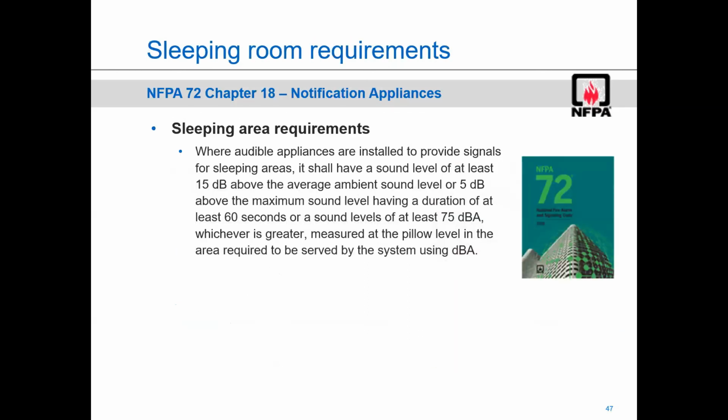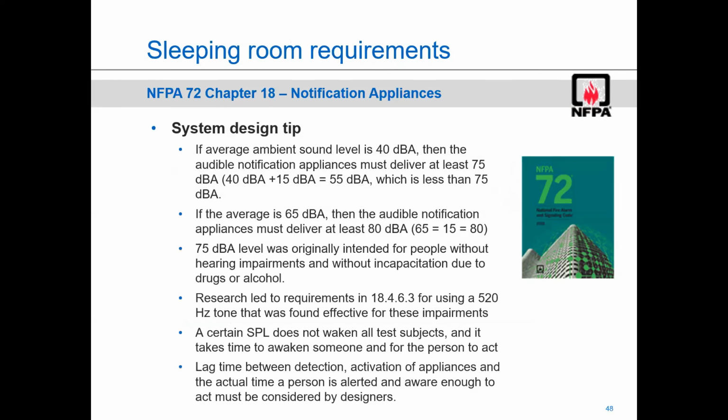The 520 hertz, or the low frequency sounder, is something I mentioned earlier. That 520 hertz is pretty low. It's a pretty low tone. This is a new code in NFPA. Having a speaker that can play 520 hertz is important. If it's above the frequency response, it's going to be a distorted, clipped sound. Not going to be able to hear it. And they're just going to continue.